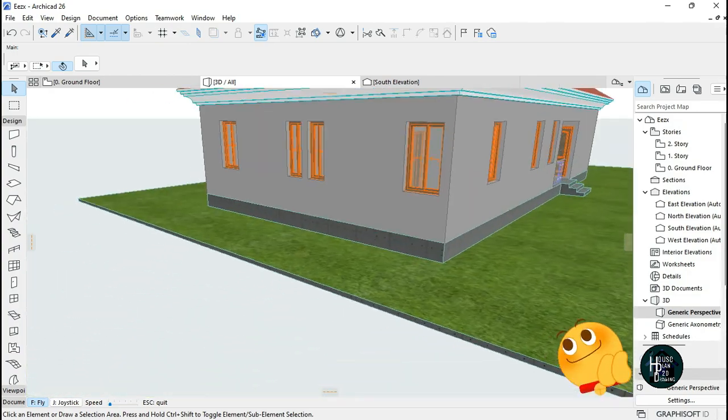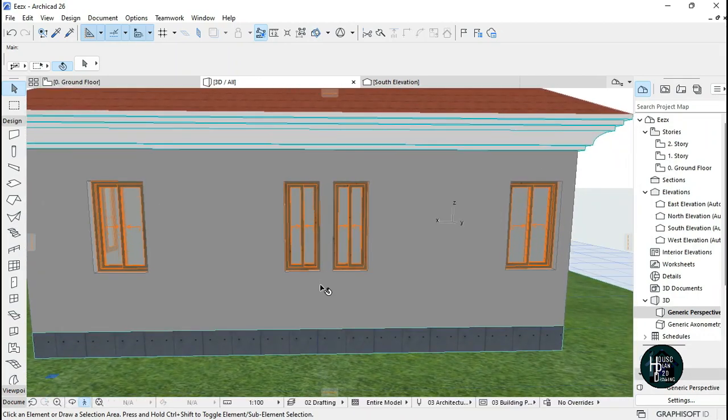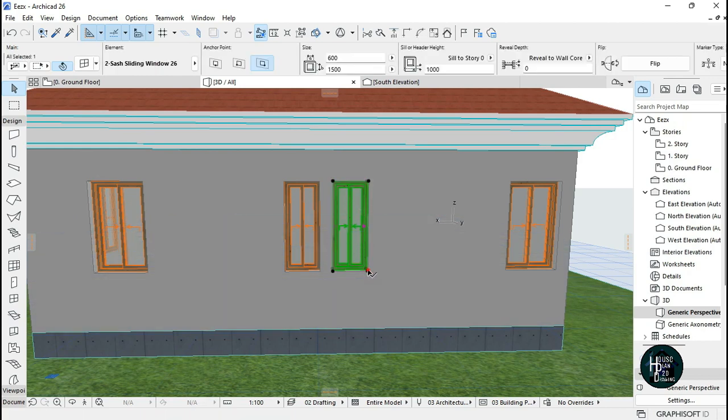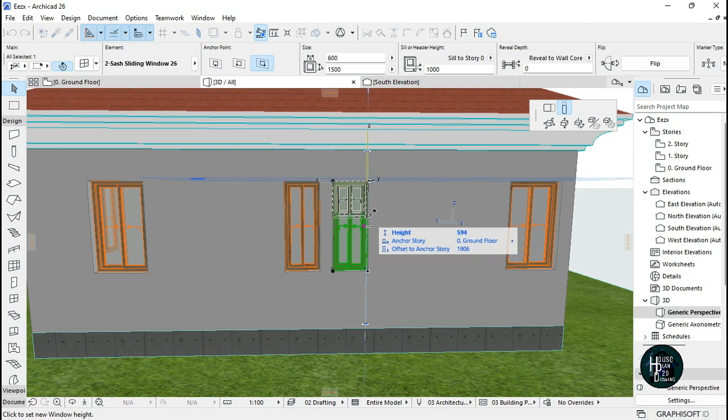The next thing I want to show you guys, this is the toilet. Okay, this toilet, you can have this kind of a window. So I'm going to try and reduce the window. For me to do that, I'm going to click on the window. Okay, click this point here. Make sure you select this straight vertically. Okay, take it up and give the distance. Allow the height to be 600.